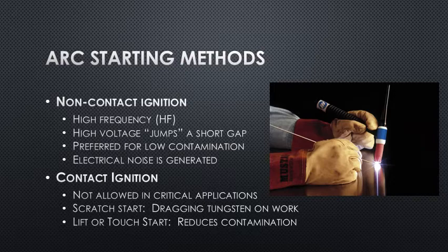So lift arc and touch start are two different features developed by power source manufacturers that use a sensing voltage before they turn on the output. As you make contact with the work, the output energizes, and when you break contact, you have a nice arc start without welding the tungsten to the work. Sometimes you may see that used, and many times that's preferred out in the field when we don't have high frequency, or when you can't use a remote control to engage the high frequency. In many cases, then, scratch start or lift arc is preferred.